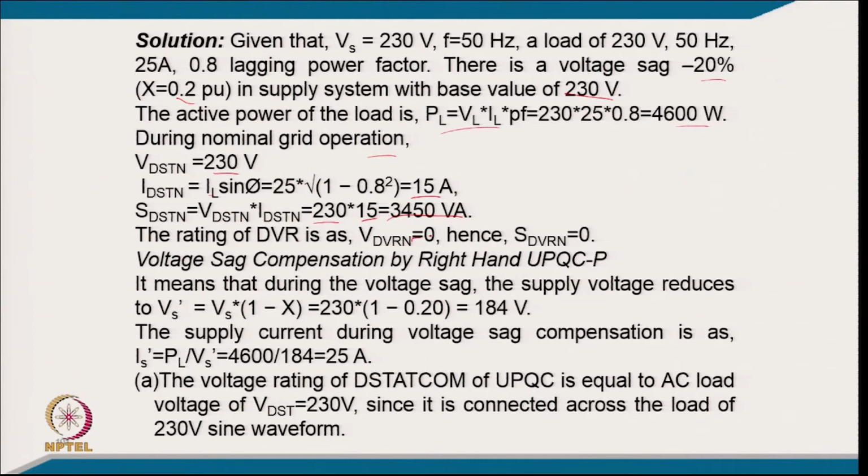The DVR rating is 0 because of the nominal condition, we are not injecting any voltage, and so there is no action of the DVR, but the D statcom still has to correct the power factor to unity.